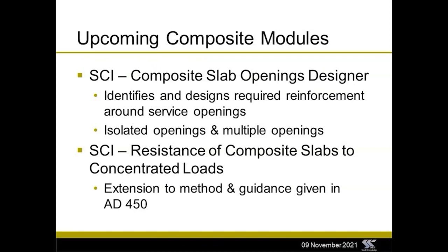And what the module will be doing is identifying and designing the required reinforcement that will be needed around these service openings to carry the loads. The module will be able to deal with isolated openings and openings that are potentially close enough to each other that they interact, so you need to design it as a single larger, what we call multiple opening.